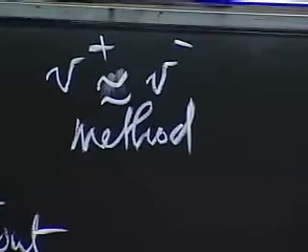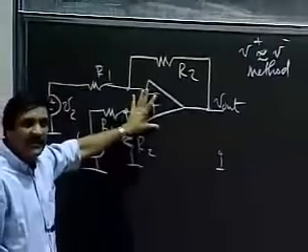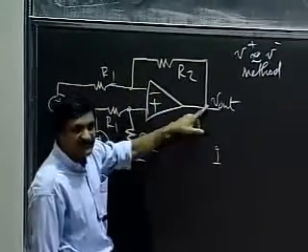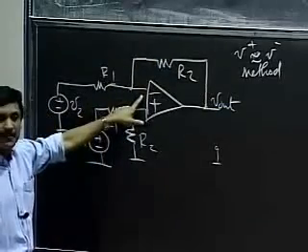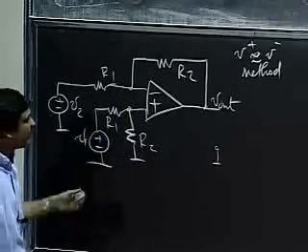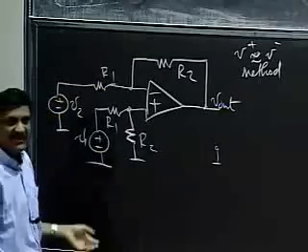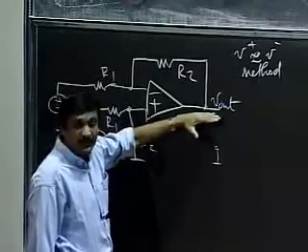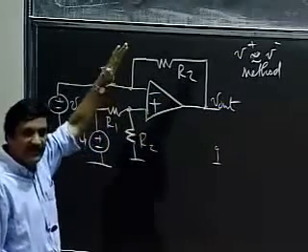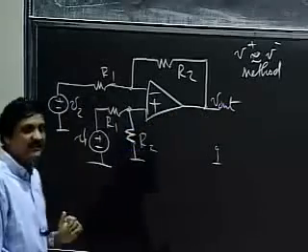So the insight here is that whenever I use the op-amp in a way in which I'm giving it negative feedback, so I'm feeding some portion of the output to its negative input, that's one property. Second property is that my inputs, V1 and V2, and my resistance values are chosen such that the output is not in saturation. So the op-amp is not at the plus Vs rail or minus Vs rail. Rather, it's somewhere in the middle in its active region.